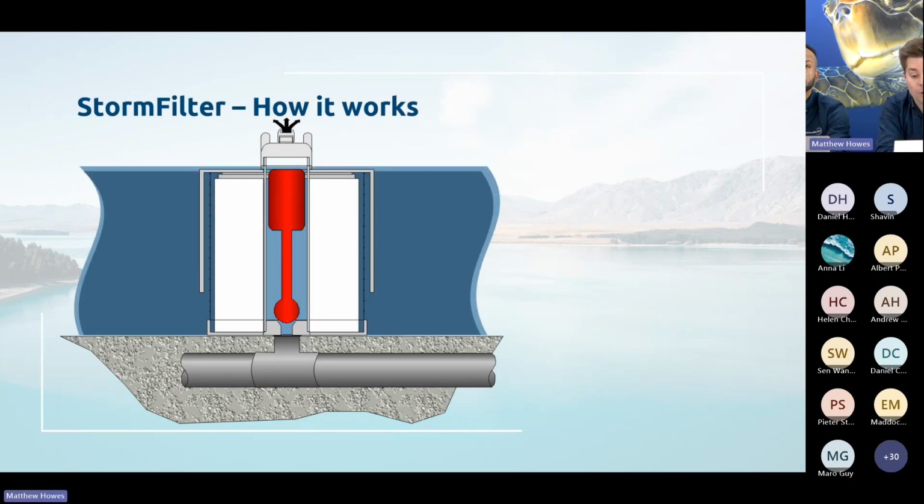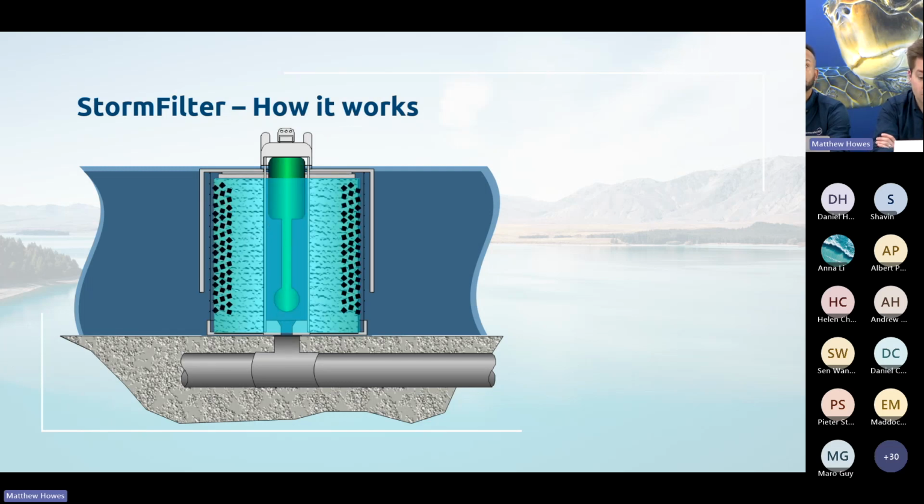Storm flows then flow into the cartridge bay and into the cartridge. As the water level rises, air is expelled from underneath that hood via a one-way valve. Once the water level is at the top of the hood, the float and the ball valve then rise to allow water to flow to the underdrain manifold through that central column. Through this process, we start a siphon. So the water is flowing horizontally through the media, but across the whole height of the cartridge.